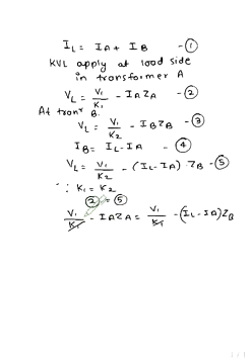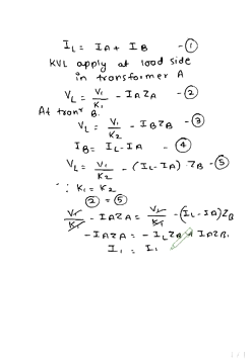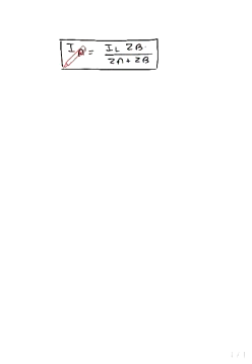So there are two equations. One is VL is equal to V1 upon K1 minus IA ZA, and the other is VL is equal to V1 by K2 minus (IL minus IA) ZB. We can equate equation 2 and equation 5. Since K1 and K2 are equal, V1 upon K1 minus IA ZA is equal to V1 upon K1 minus (IL minus IA) into ZB.